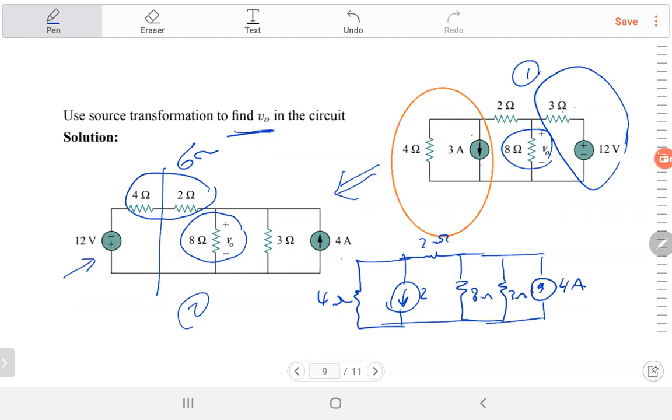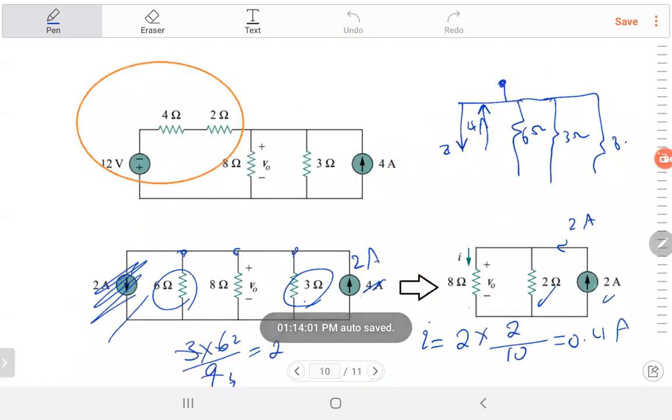But do you think it's still easy? Yes, we can solve it, but you are going to write equations. If you have current source, we use the first method that we explained previously, the nodal analysis, and make a two by two matrix. But you can get rid of this too if you convert this to voltage source and you add it to it. It made life easy. In the end, you have only one current source and 2 parameters. It doesn't need skills. It's like you have to focus and think about how you can simplify it. That's all. It doesn't have any complexity.